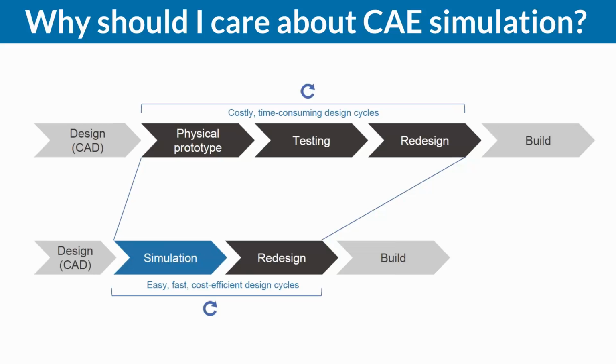Also, if you use simulation, you should not skip at least the final physical test. But without using simulation, the test has to be done for every product iteration, every design iteration, every increment. And before the testing, you need to make up your mind what you want to test, where you want to place probes, which results you want to get out of the test, to make any informed design decision based on the test.